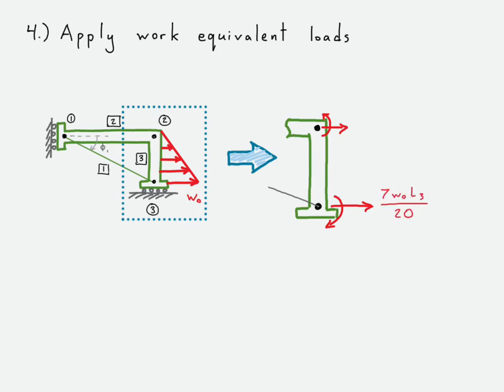And so if you did that, you would get the following force and moment at the bottom node where the bigger part of the triangle load is. You can get the following for the top node where the triangle drops down to 0. And then we just substitute that. We'll say, well, this will be the load for the horizontal force at node 2.